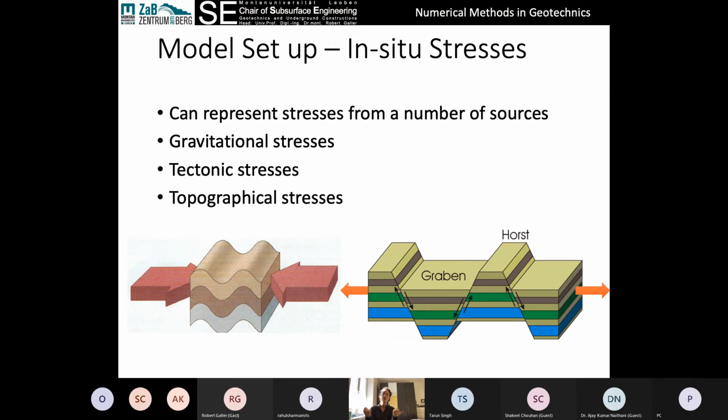So in that case, we have very, very low horizontal stresses in the pulling direction. So getting a feel for those stresses, and there are lots of courses in site investigation, rock mechanics and soil mechanics for estimating those stresses. But it's important to not just use the depth and the overburden for sigma v when you're in a deep tunnel. You also have to consider